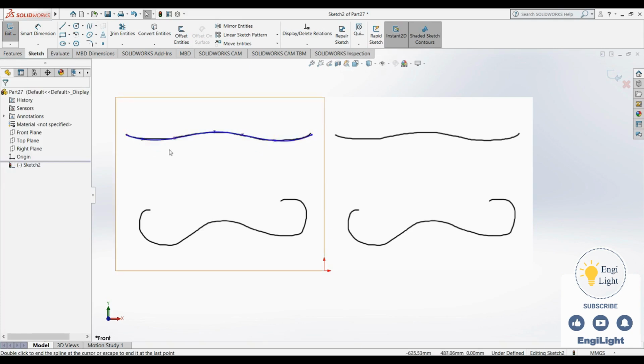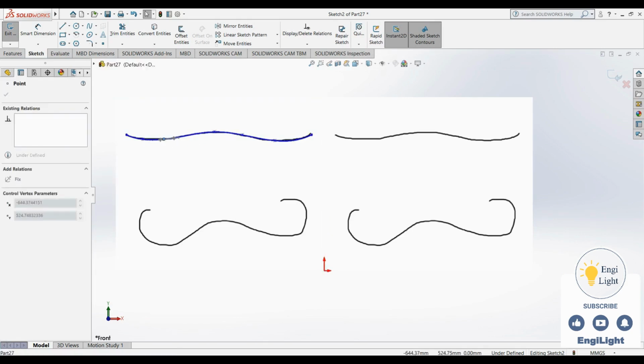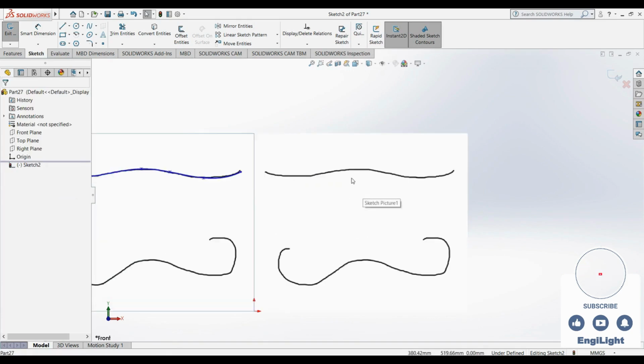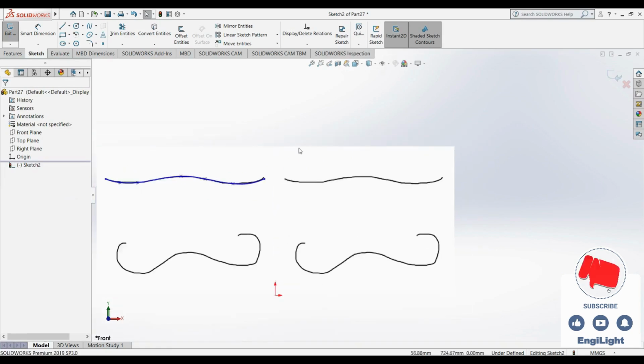This way, I'm tracing the curve so it perfectly matches the line in the reference image I prepared earlier. Okay, now let's draw the same line again using the Style Spline tool. I see 3 distinct curves, this one, and this one. 3 inflection points mean we need a degree 4 Bézier. That requires 5 control points.